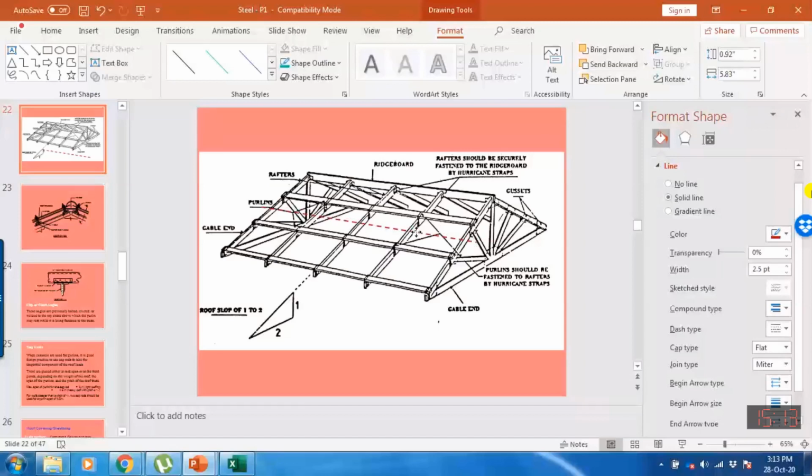On this panel, we will design the interior purlin and the same purlin will be used for the exterior. Actually, the load is acting in this segment. Half of the panel load is coming on this panel and half of this portion's load is going to the other purlin.